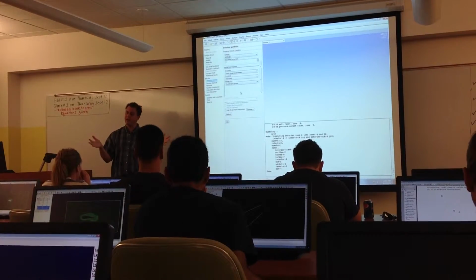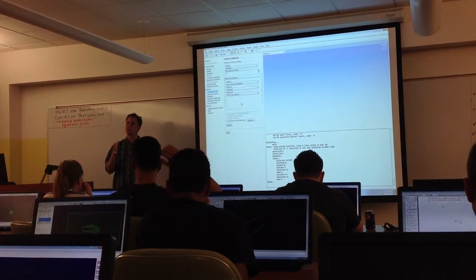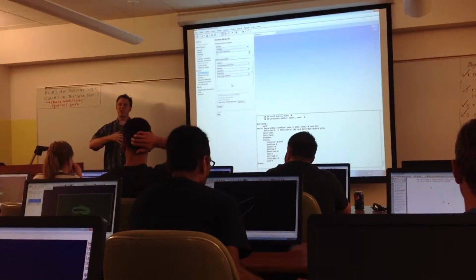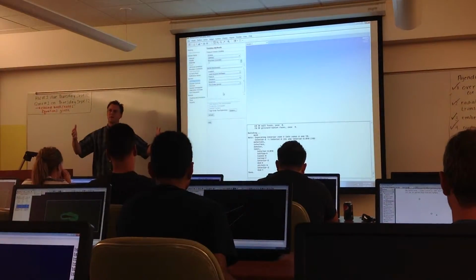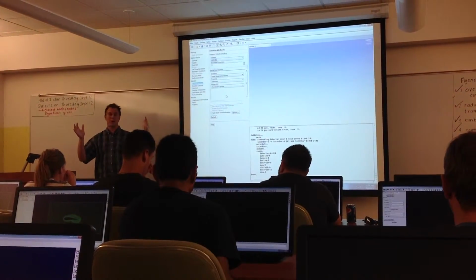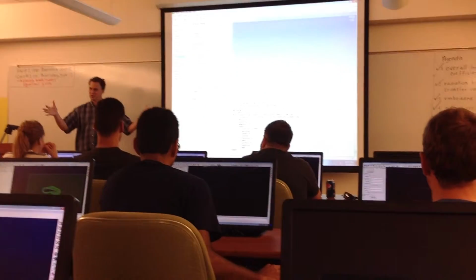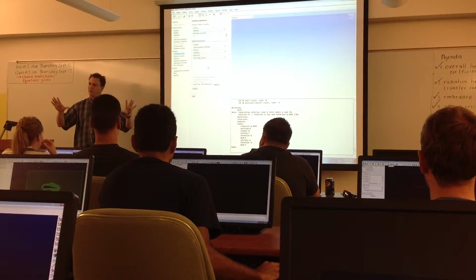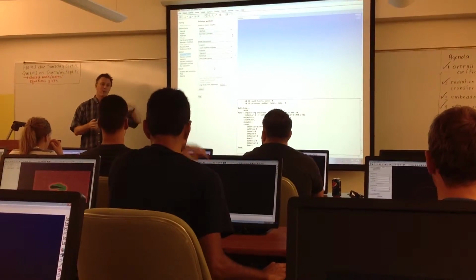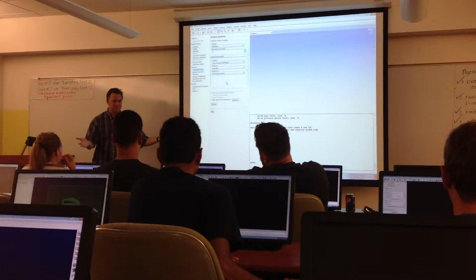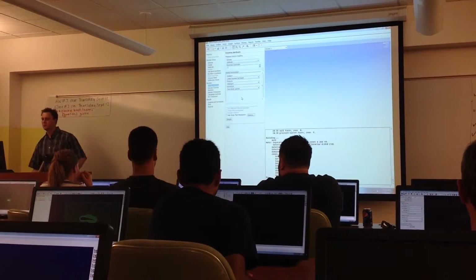And why would you want to do that? Only because it keeps the solution very stable. You get a nice stable development of the flow. Nothing crazy develops. It's not the right answer, but it gets you started. Once you've got that established, then I can turn the second order on, and I get rid of that safety net, so to speak. So first order.